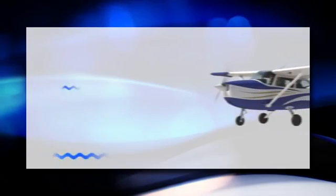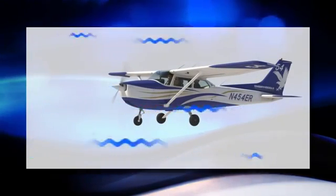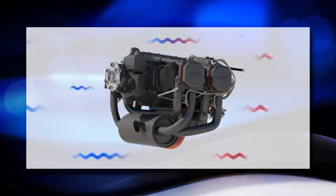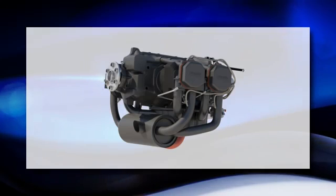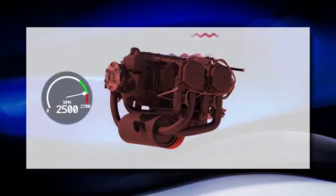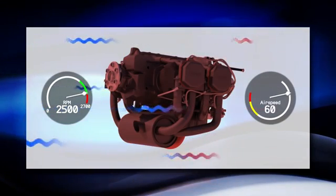However, we also use air to cool our engines. As the airplane flies through the air, outside air flows through inlets usually found on the front of the airplane like the Cessna 172. This outside air is colder than the engine, so as the air flows over the engine, it cools it in the same manner that the oil cools the engine. This method of cooling can be severely restricted, however. When the airplane is running at high power and at very low speed, such as when climbing, airflow is minimized,